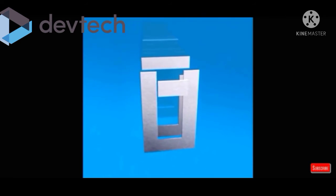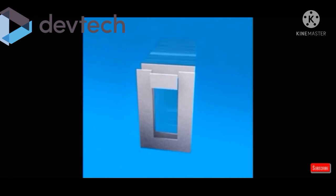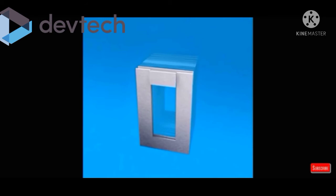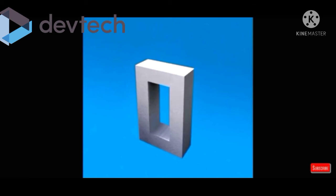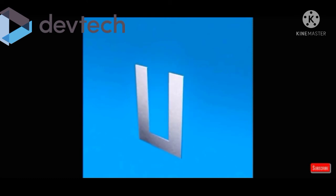To reduce these unwanted power losses, thin steel laminations are used to construct the transformer core. Laminations are made up of a highly permeable material, that is silicon steel. These laminations are assembled together to build a solid core. The resistivity of the steel sheet itself is high, reducing the eddy current losses while making the laminations very thin.